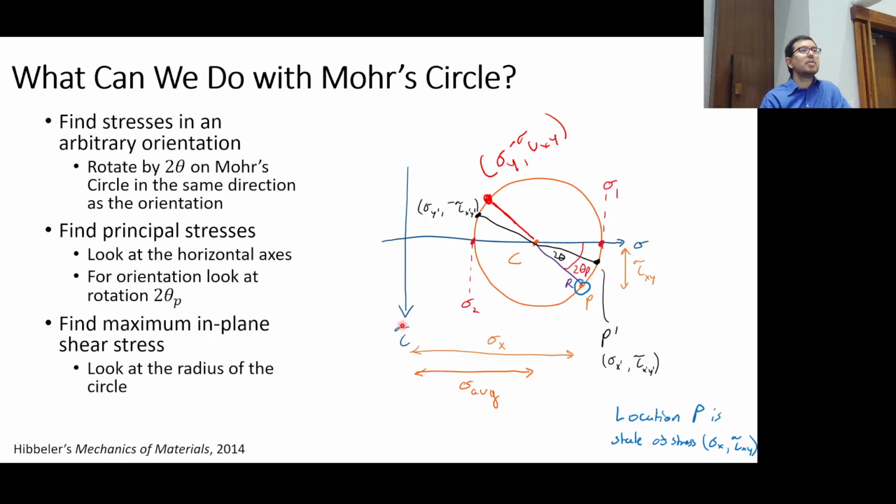Where is the maximum going to be? Remember, you cannot leave the Mohr circle. You must be on the Mohr circle. You cannot move the Mohr circle, you cannot change the radius of the Mohr circle, unless you change the magnitude of the loads. So where would it be? Yeah, so it's going to be up here and down here, right?